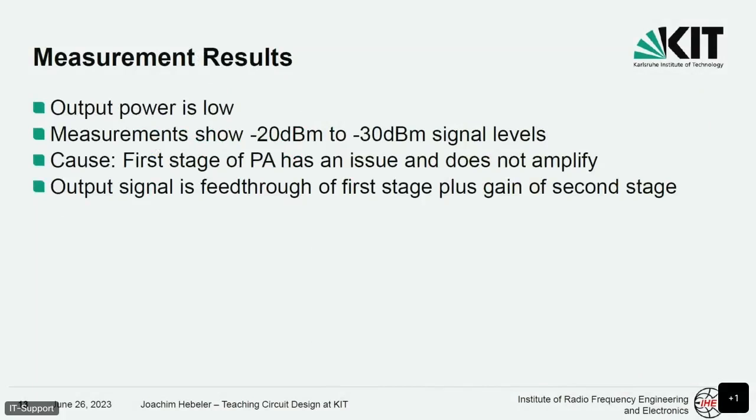Because, I mean, it's RF design. You have to think about all these inductors. An inductor is just a piece of wire. The LVS doesn't care if this piece of wire has 2, 3, 5, 10 turns, but the amplifier cares. And somehow this first stage amplifier doesn't work. Well, what you could measure was the leak-throughs through the amplifier and then just measure the output and see there, okay, the pattern is there, so if the amplifier would work, this would also work.